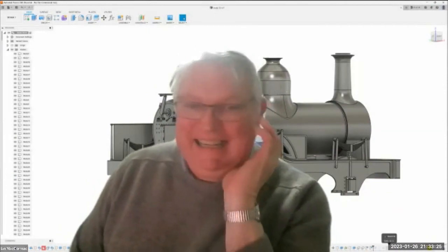James, going back to the discussion about cleaning off afterwards, John Walker said, after washing in the wash and cure, I rinse with clean IPA through an old airbrush, and that removes sticky residue. And then I blow air only to dry it before post-curing. Okay, interesting. And Simon has said, I leave resin in the tank, but use a cover which was printed using an FDM printer to fit the tank from a design on Thingiverse.